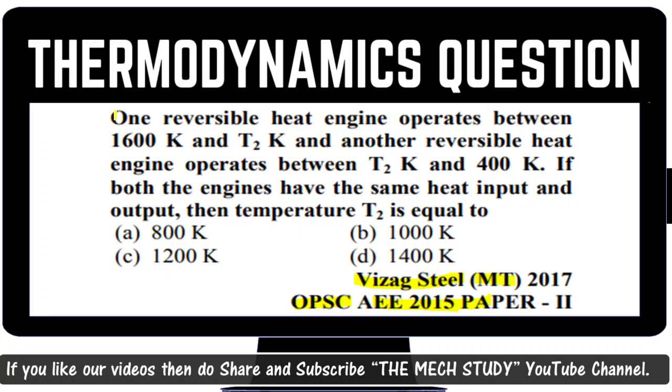In this question they have mentioned one reversible heat engine operating between two temperatures, 1600 and T2 Kelvin, and another reversible heat engine operating between T2 and 400 Kelvin. If both engines have the same heat input and output, then the temperature T2 is equal to what? These questions are almost the same as the previous question, just with the wording framed differently, and you need to calculate the temperature T2.